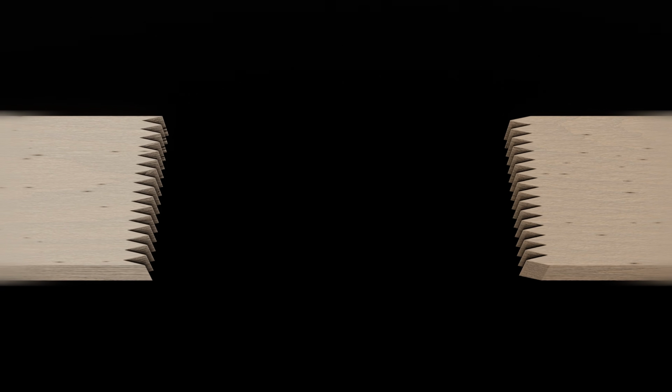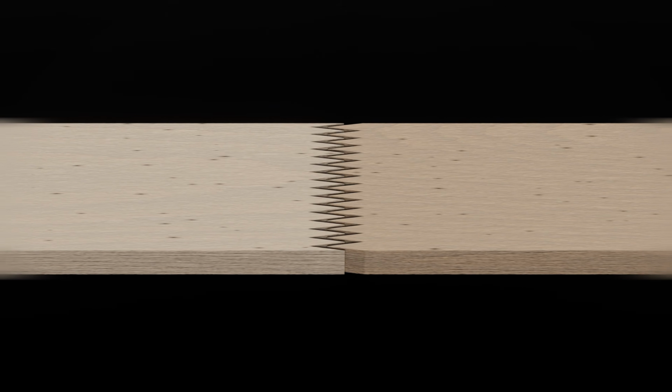In order to create incredibly long planks, shorter planks are finger jointed together. Finger jointing works by cutting the sides of the planks into zigzag patterns. This allows two planks to easily slide into each other. One of the two planks gets adhesive applied to it before sliding a second plank into it. After finger jointing, the planks are stored somewhere to let the adhesive dry and let the planks bond together.